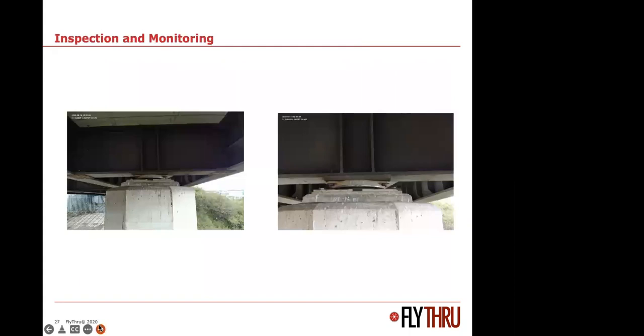Now these two images are taken from 5 meters away. They're simultaneously captured. One's the wide angle, one is the more zoomed, but it hasn't been zoomed in at all. Those are the images that we give, or actually were taken by the bridge engineers. They then zoom in on their laptops back in the office, or they've got the option of using 100 times plus digital zoom on site to be able to capture the detail of the corrosion in and around those bridge structures. There is no other way, apart from putting a very long pole with a camera on the top of it, of capturing that data.